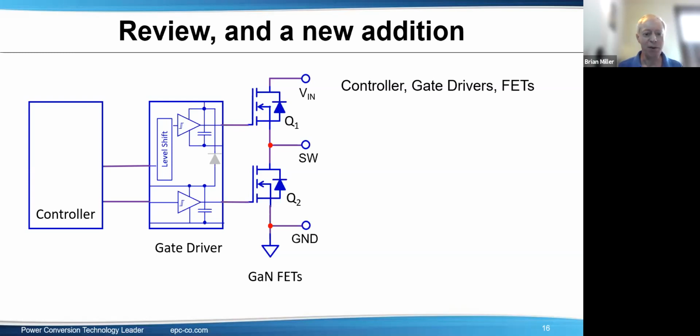There's a few cases, for example, in motor drive where you have a huge amount of GaN FETs in parallel, like over 10, I think over 12, up to 20, driven by one gate driver. In situations like that, things can maybe get out of control and additional capacitors, gate to source, might be needed, but I just don't see external circuit modifications needed for that.